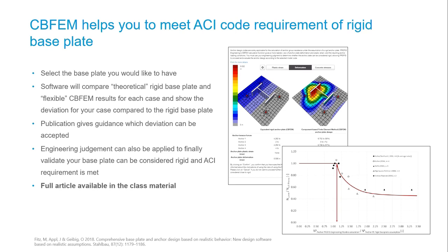Just to make sure, because we're always talking about a realistic picture, right? You want to map what will be there in reality, more or less. And that's why it doesn't help if you just say, okay, I just take the steel stiffness of the anchor and that's safe. That's probably an approach you would take in a Robot structural analysis or whatever. We have seen that especially for anchors with less stiffness, you see a completely different behavior of the whole connection. That's why, as I mentioned before, all these combinations of these parameters are important.